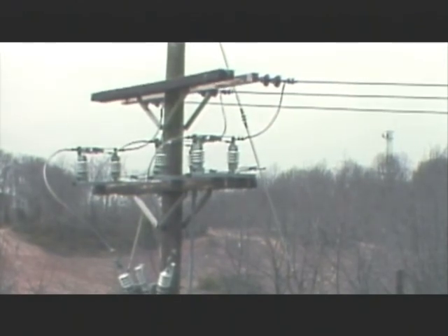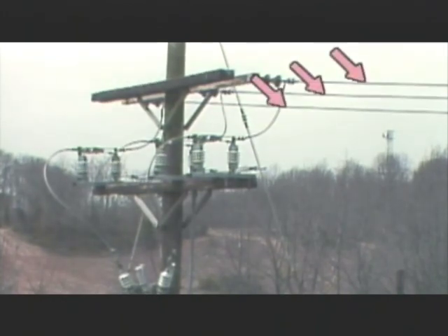In most systems, primary distribution voltage originates as three-phase power. Feeders, sometimes called primary mains or mains, consist of three individual wires that are buried in the ground or strung overhead on utility poles. Each one of these wires carries one phase of a three-phase feeder.